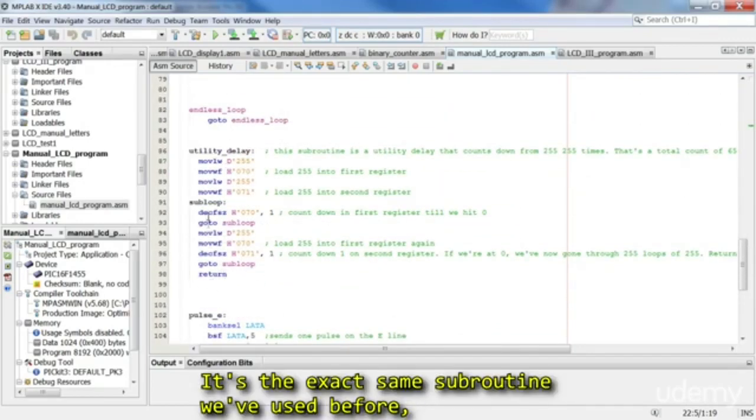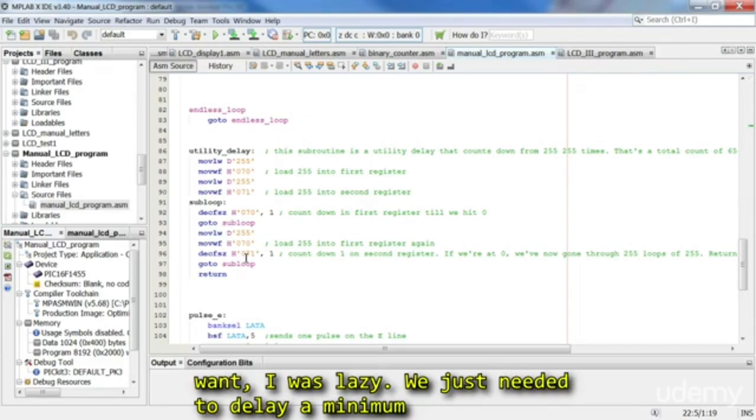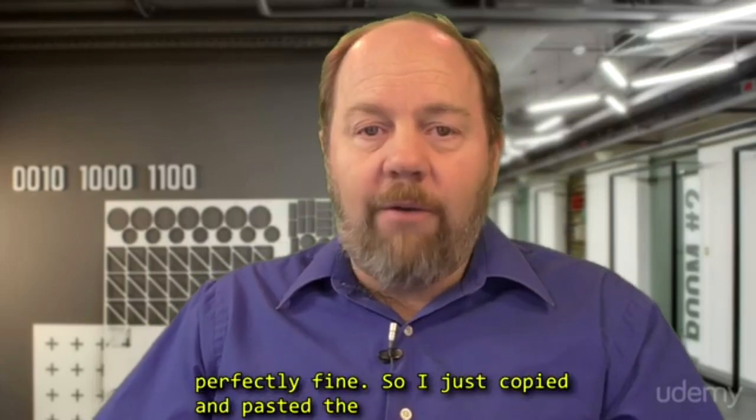It's the exact same subroutine we've used before, but bear in mind, we're now running at 1 megahertz, not 16 megahertz. So this whole delay now takes approximately 0.8 seconds. Now you can change these numbers if you want. I was just lazy. We just needed to delay a minimum of 15 milliseconds. If you delay longer, that's perfectly fine.